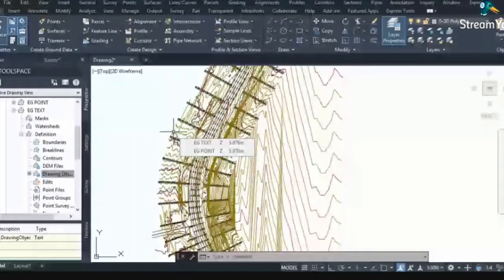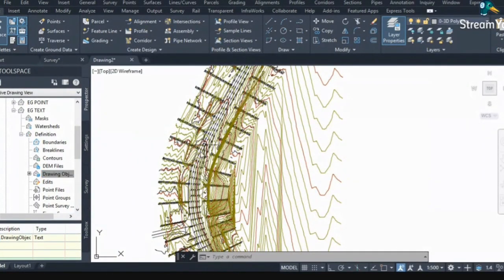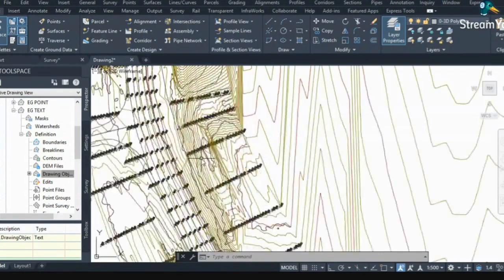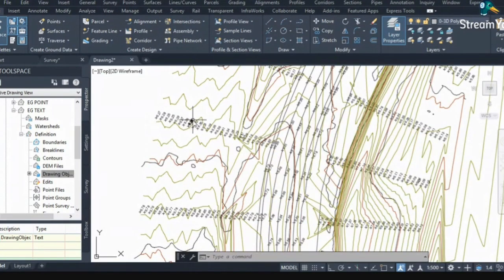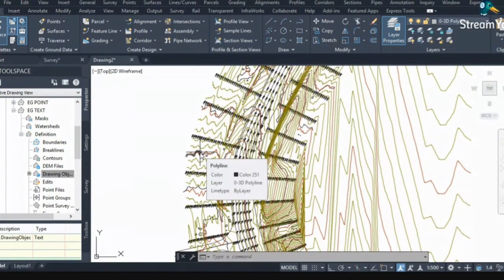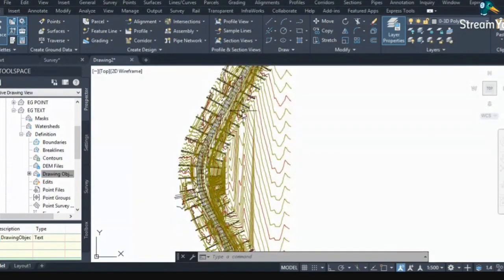And like I said, this is the way you can set up a drawing. Always create a new drawing, new design file, and only bring the data which you require to create the surface. You can keep those survey files as an X-ref in the background to look at things, so that it is not heavy. Right now I copied everything, but you can copy only the data you need to create the surface. So this is why you can keep your file light, and you can easily work on these files. So yes, that is how you start your design. This is the first step.